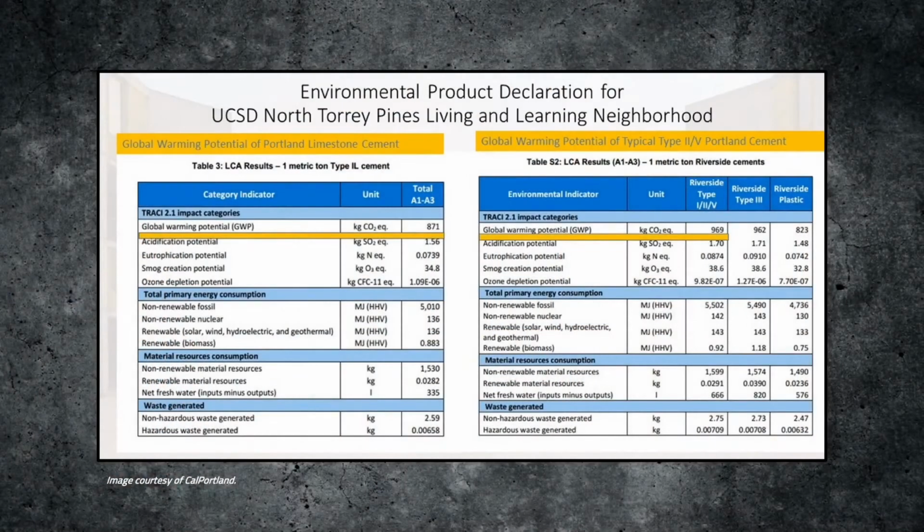Many concrete companies have published EPDs for concrete, and most would be willing to publish EPDs specifically for a project. NRMCA has published a cradle-to-gate life cycle assessment of ready-mixed concrete and an industry-wide EPD for concrete. Armed with this information, you can conduct an LCA to determine the embodied impacts of concrete of a benchmark building using typical concrete mixes with typical amounts of SCMs, and a proposed building using concrete mixes with high volumes of